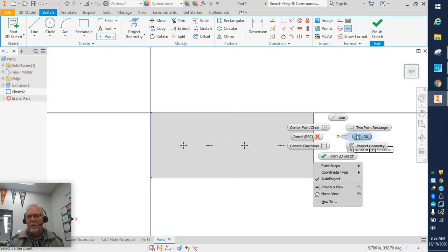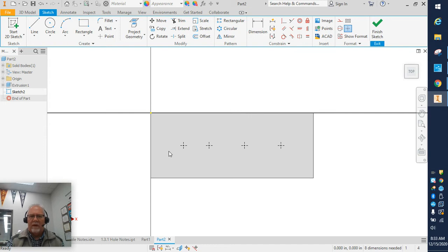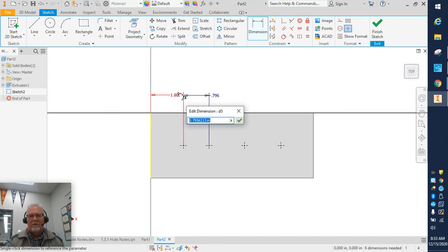It's going to save us one step later so I don't have to get these dimensioned this way. Now I can go ahead and dimension from the edge to here, 1 inch. And I'm just going to chain these just for the sake of what we're doing here. It's efficient. I'm just going to click on the previous dimension so it makes it the same all the way down.